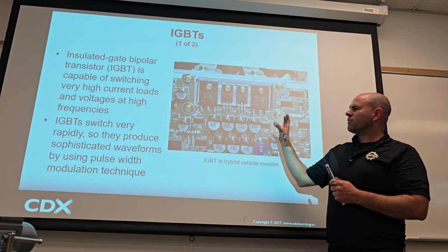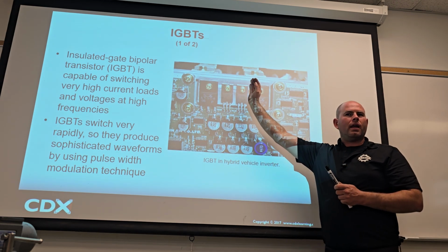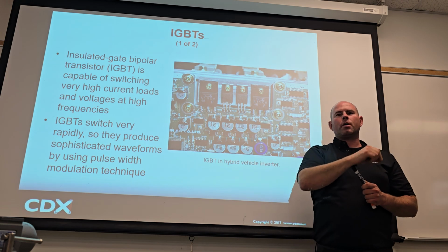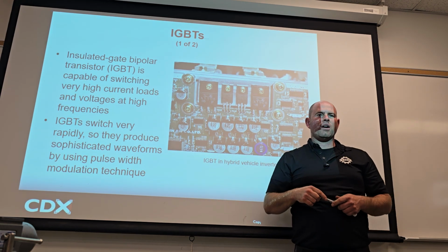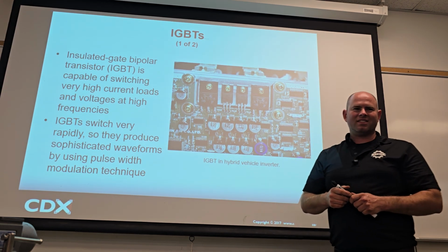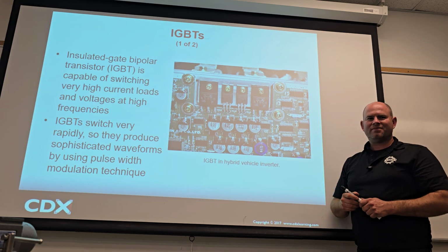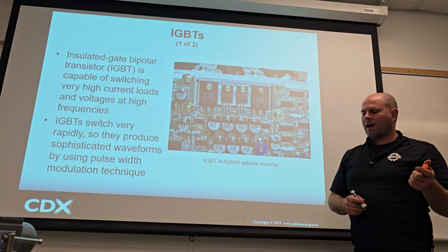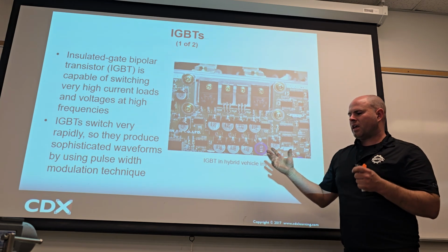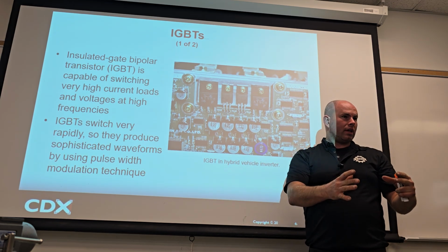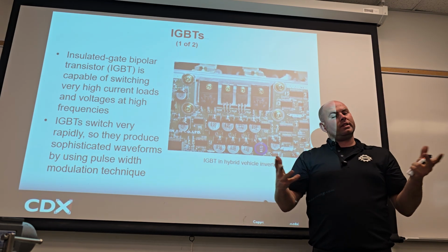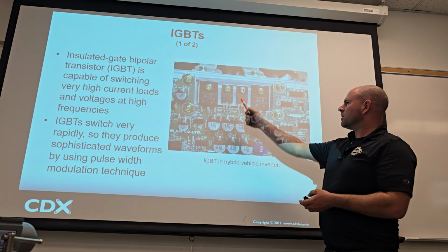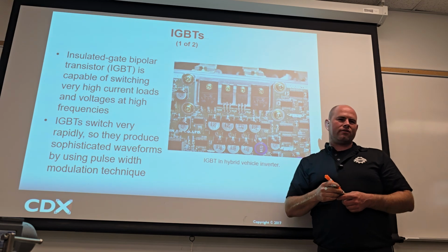So this inverter has coolant going through it, and it has an electric water pump to pump the coolant. And if the electric water pump fails and this overheats, all bets are off. Yeah, I can imagine that, because it's very high power, so it gets really hot. Exactly. Or another thing that's happened is where they put the inverter is right under the hood. And if you get in some sort of front end collision, the inverter's right there. So we're changing the inverter because it's broken, not necessarily because one of the electronic components failed.